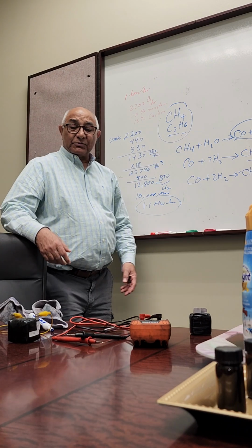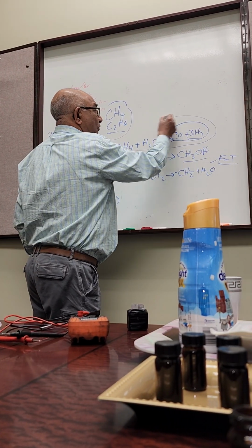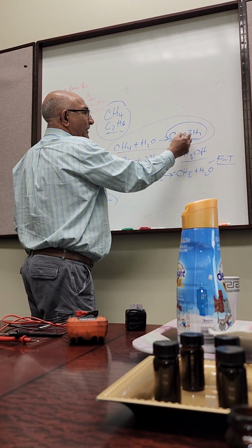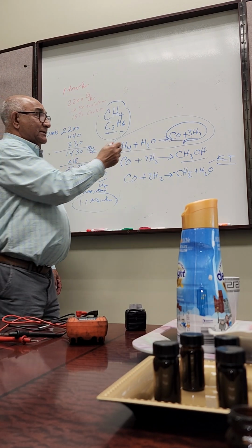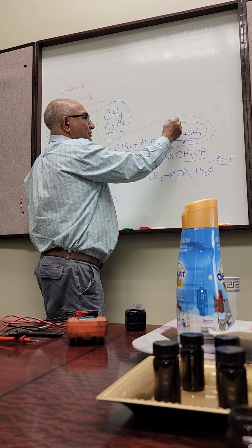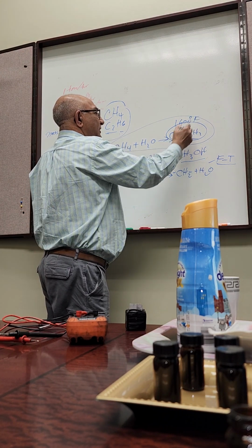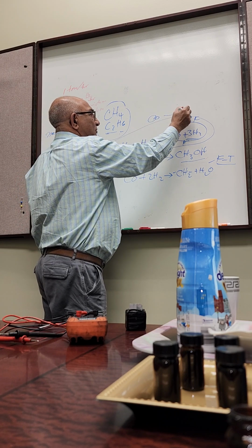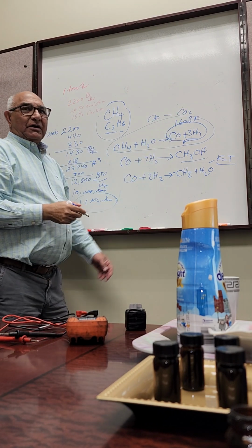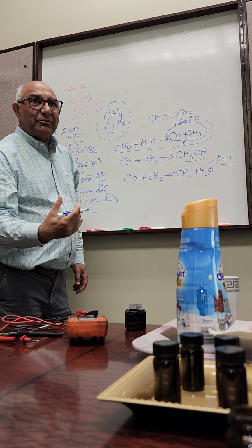If you want to produce a liquid fuel after that, I normally go to CO, carbon monoxide. This requires high temperature, so we have to go to about 1,600 degrees Fahrenheit. But there's a competition between CO and CO2. The CO2 is produced at lower temperatures.